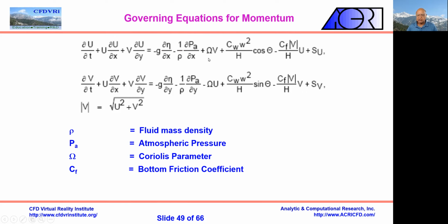Okay, this is the Coriolis constant. This is because the curvature of the Earth imposes its own Coriolis force, right? And then we have the wind at the top. Okay, the wind is blowing at the top. So this is proportional to the square of the speed of the wind, an empirical coefficient, and the direction of the wind. And then finally, at the bottom, we have the skin friction due to the roughness or friction at the seabed, right? The water is rubbing against that, losing energy.